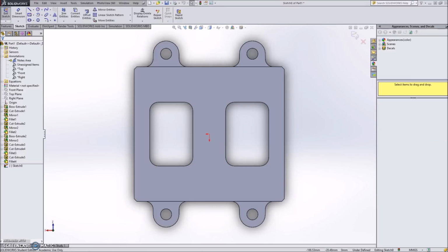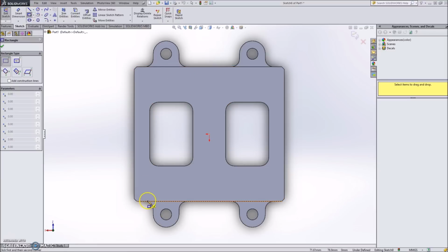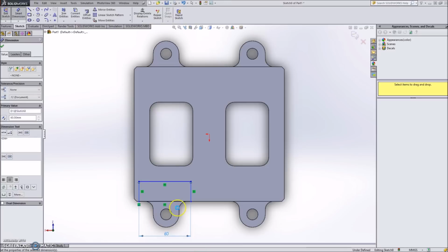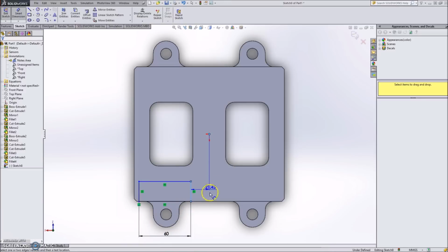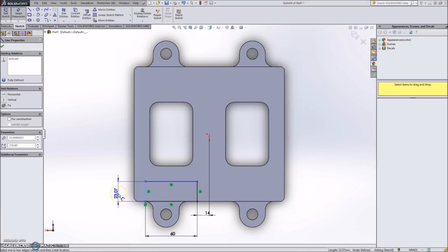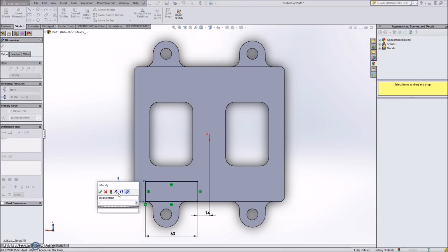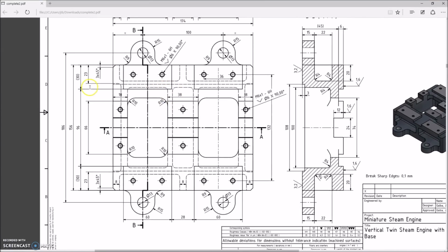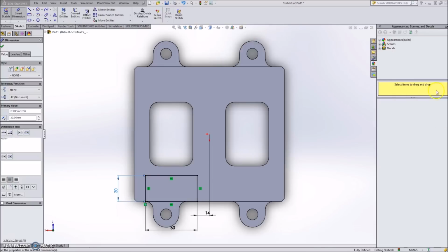and we will start with drawing the tabs on the sides here. So I'm actually going to switch to a corner rectangle so that I may start with one corner along this edge, and these slots are 60 millimeters long. They are 28 millimeters apart, so 14 millimeters from the center. And lastly, we can see that they are 30 millimeters deep, I believe, if we take a look. Yes, we see they are 30 millimeters deep.